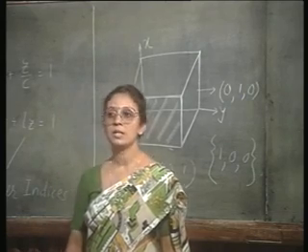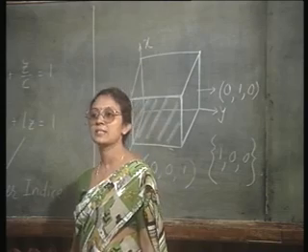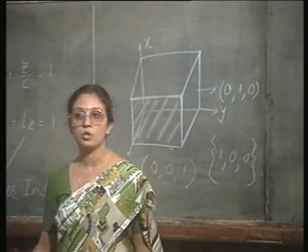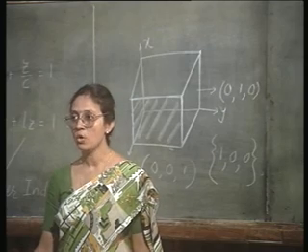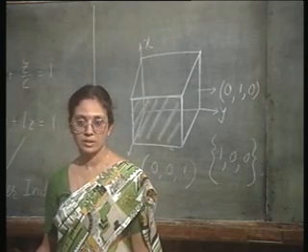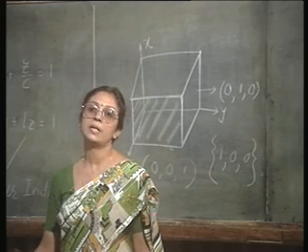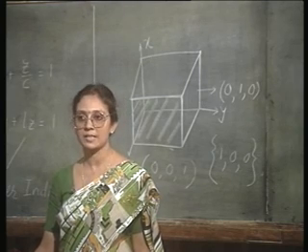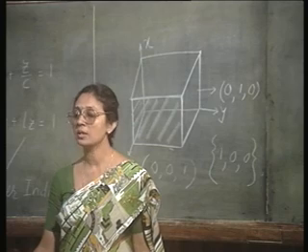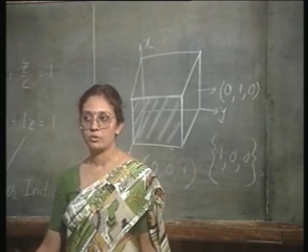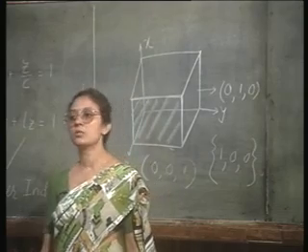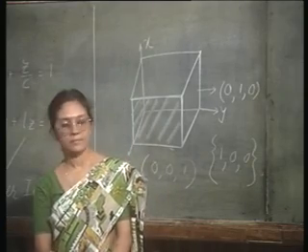When I am putting the Miller indices inside the second bracket, I am referring not to one particular plane, but to a class of planes which makes collectively all those make intercepts only on one axis and are parallel to the other two axes. They are referred to as 1, 0, 0 planes.